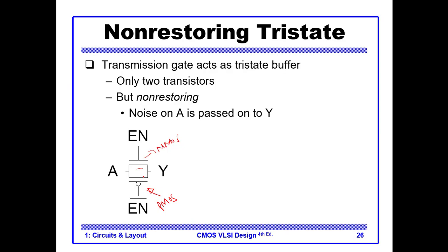But this kind of transmission gate has one problem. Remember that other gates were regenerative, they were restoring, but the transmission gates are non-restoring.